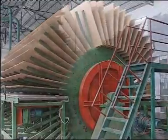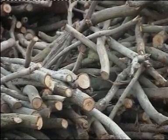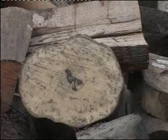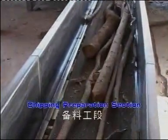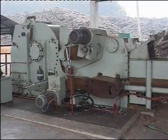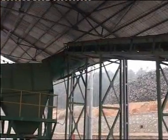Most of the raw materials used in MDF production are wood materials, such as branches, small diameter wood, leftovers of timber cutting and wood strips, round wood core, and veneer withes. The wood materials are turned into uniform wood chips by drum chipper via feeding belt conveyor so as to facilitate transport, storage, and fiber making.